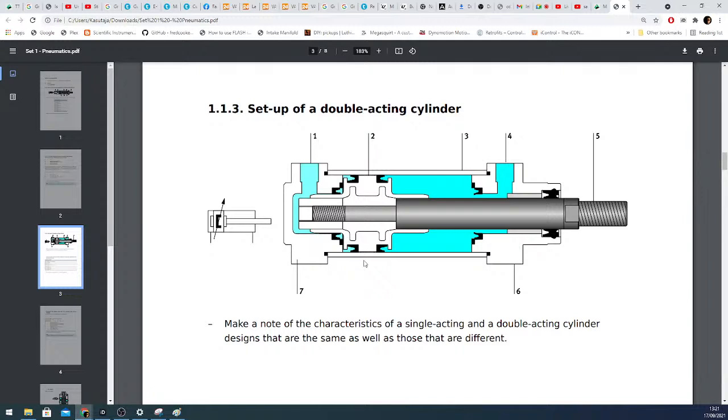Usually, if possible, we try to use the back side of the cylinder for the actions where we need the cylinder to move, because when we pressurize the back part, we have more seals in front of the compressed air before the end cap, so less likely to leak from the back side than from the front side. And we have more seals that are stopping the leaking process.